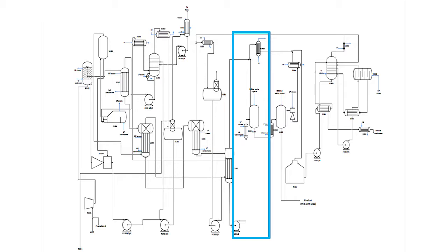This is the last section that is aimed at the decomposition of ammonium carbamate to purify the product. This purification occurs within the low pressure decomposer. The vacuum evaporation section is, as the name suggests, aimed at concentrating the urea solution through evaporation of any remaining water. The urea liquor is transported from a preheater into the first vacuum evaporator through a heating element before making its way through to the prilling column.